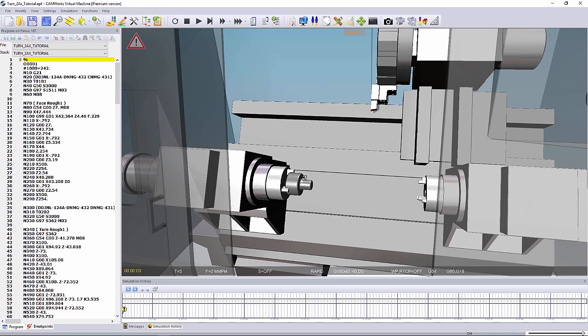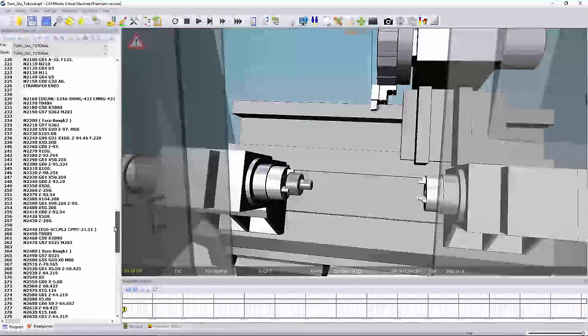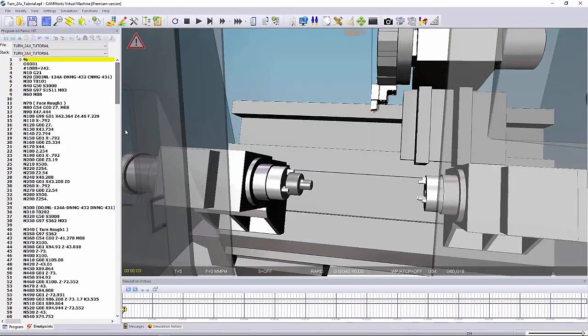I can turn collision checking on. I can turn it off. I can tell it to check but just push through it and notify me when it collides. I can start from the beginning of the Gcode, and I can start on any line I want to. So I'll kind of walk you through what all of these look like.